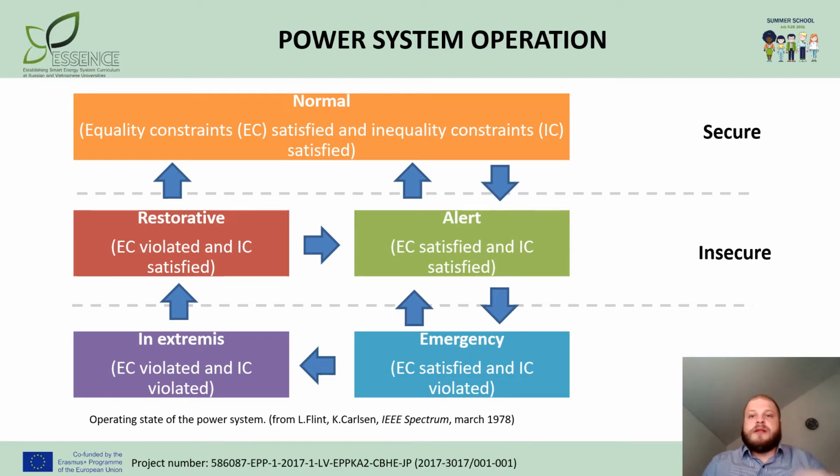Once the total collapse has been halted, and some equipment has been restarted or is operating within rated capability, the system could enter the restoration state, with control action being taken to pick up all lost loads and reconnect the system. From this state, the system could transit to either the alert or the normal state, depending on the circumstances.